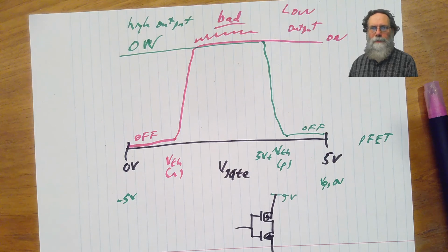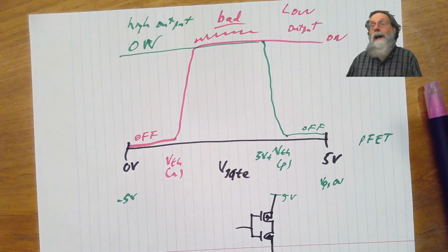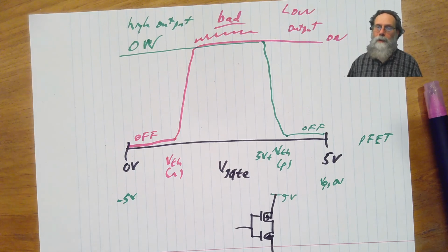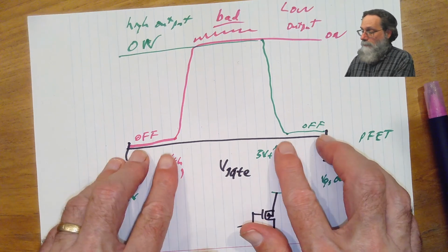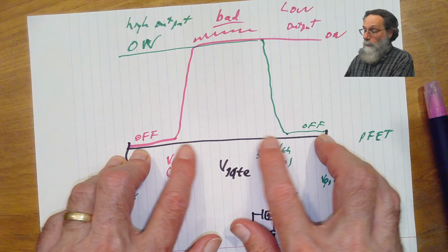That's great for doing very low power things, but if you're trying to do something like a power amplifier where you want to be able to put high voltages and high currents, because if you're driving a loudspeaker for instance and you have an 8 ohm load, you can't just say, well, I'll put a tiny little voltage there because then you won't get any power to the loudspeaker. You have to go with a large enough voltage for the circuit you're driving, for a loudspeaker, for a motor, anything where you're trying to deliver a high voltage to something. You don't have the choice of saying, well, I'll just make the voltages smaller. And so what people can do is sometimes they will pick transistors with big thresholds.